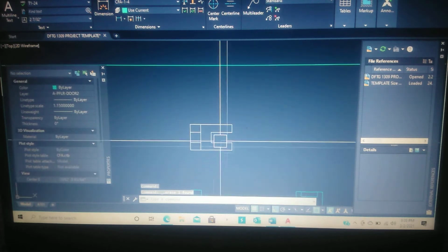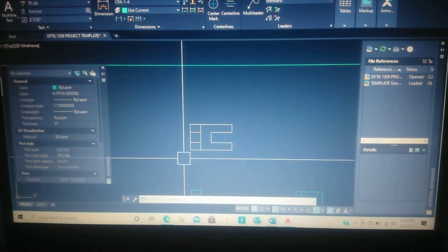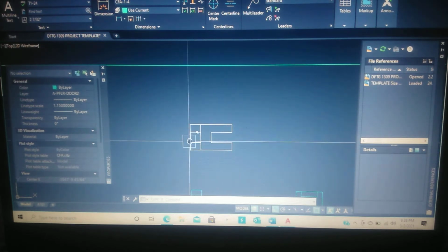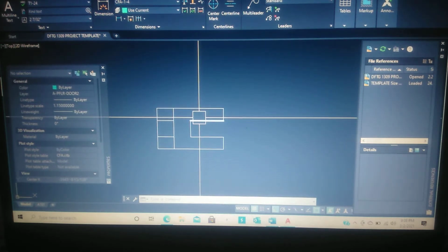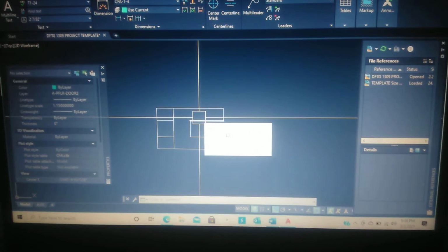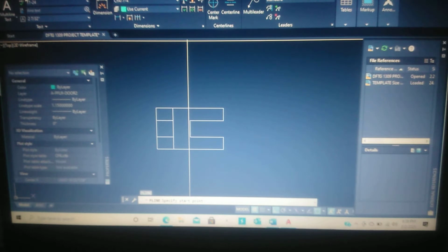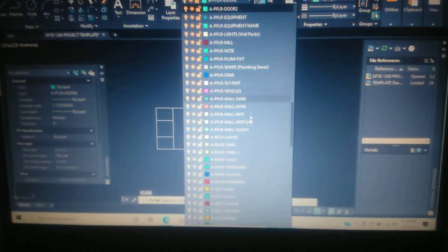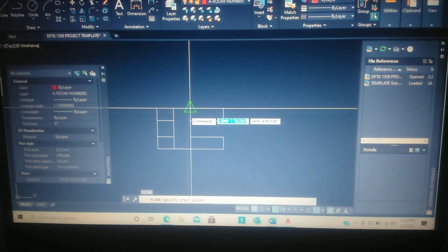Okay. So what I like to do when I'm doing 3D models is look at it in parts, okay? So right here, from this line to this line is part 1, and from this line to this line is part 2, okay? So what you can do is type in the letters PL. PL stands for polyline, okay? So type in PL and hit the space bar to activate it. And let's go ahead and go to the Home tab. And let's change this layer to something red. Let's just put it on room numbers for right now because we just want something red because we're about to overlap the lines we already have drawn and want it to stand out.